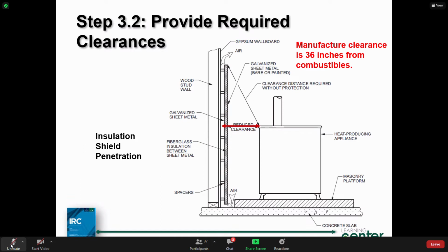But the manufacturer must allow clearance reduction methods. When this happened to me, it was an oil-fired boiler, okay? It was in a rural area. I contacted the building official at the time. I actually drew up my picture. It was similar to this here because I wanted to get an approval before we built it on the wall, right? And I did. It was back when we faxed a lot. Remember that thermal paper in our fax machines? I don't know if you remember that.